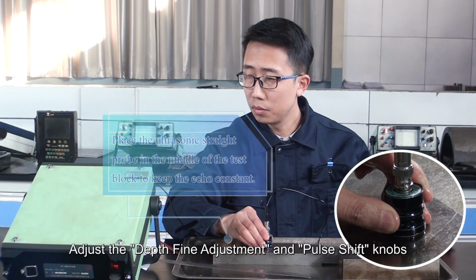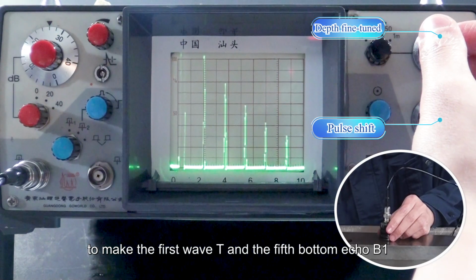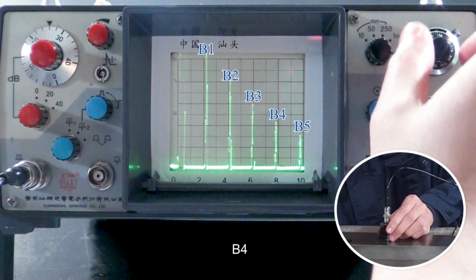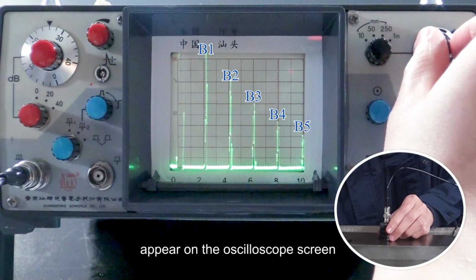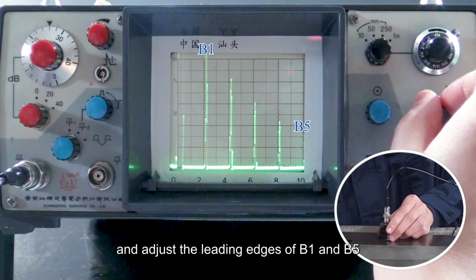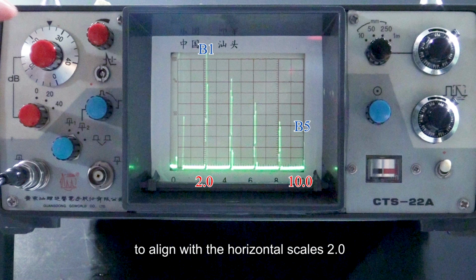Adjust the depth fine adjustment and the pulse shift knobs to make the first wave T and the bottom echoes B1, B2, B3, B4, B5 appear on the oscilloscope screen, and adjust the leading edges of B1 and B5 to align with the horizontal scales 2.0 and 10.0 respectively.